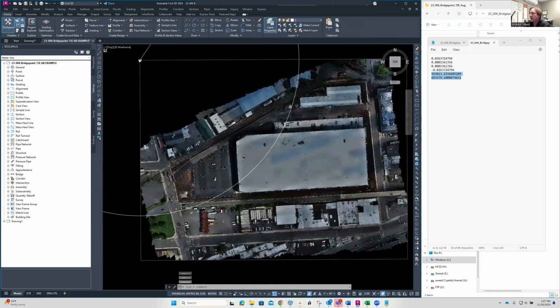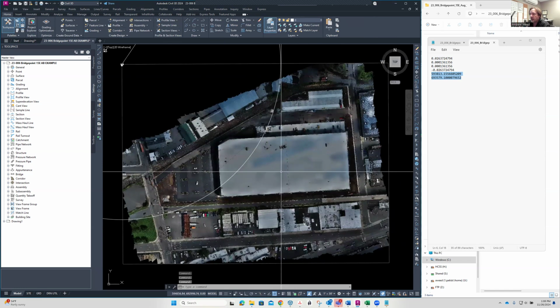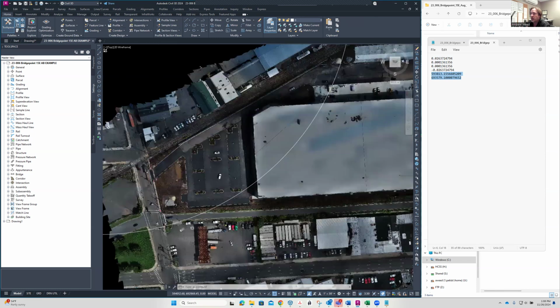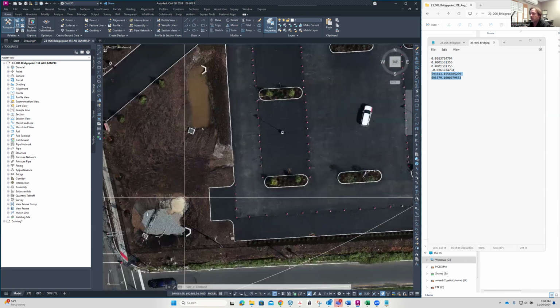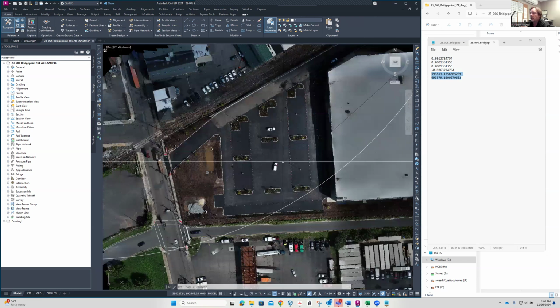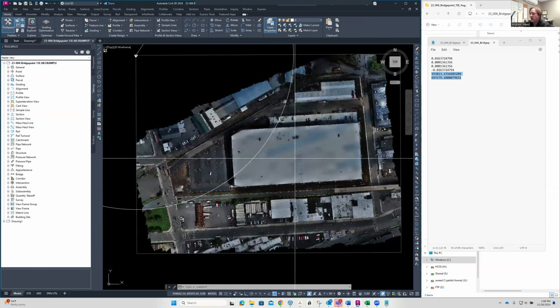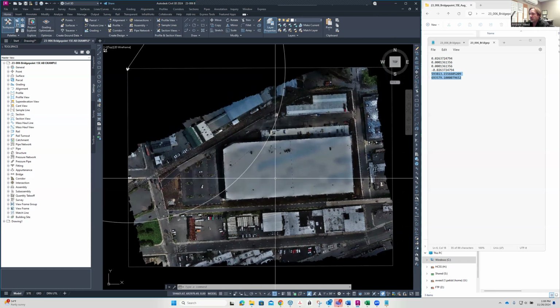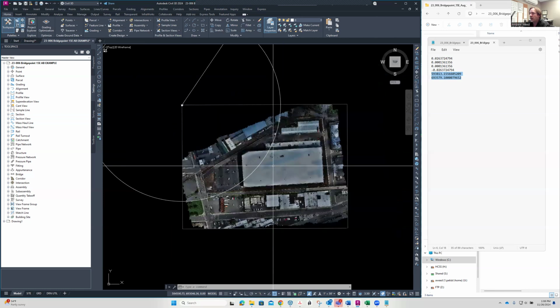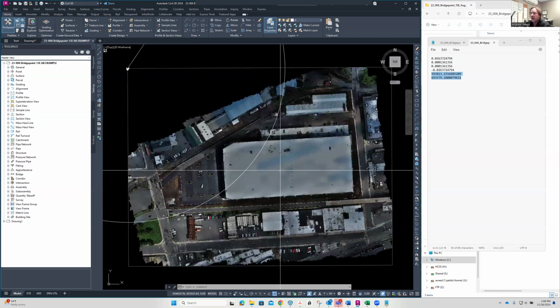And using this aerial photo, the end game for us is generally to produce an as-built survey or to pull quantities, just to say, okay, we moved this much dirt from this side of the site to the other, or we removed this much dirt from the site, or we brought this much dirt into the site. One of the outputs available for us is a DEM, a digital elevation model, or even a point cloud. It does give us rough topography, so we can actually compare surface to surface.